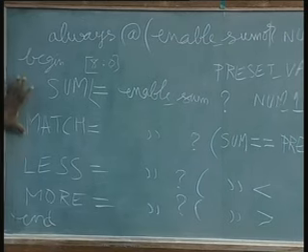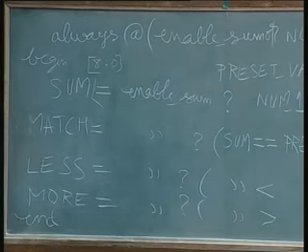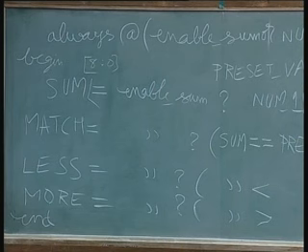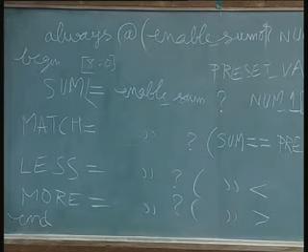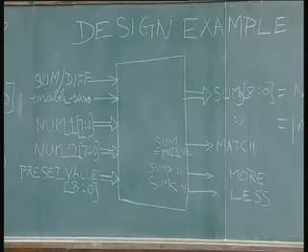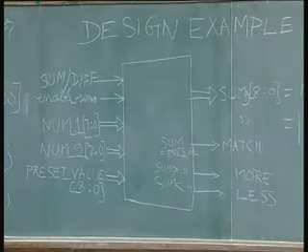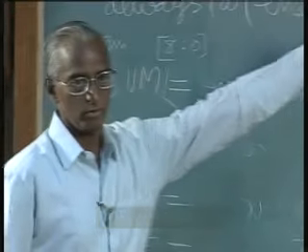But when you put assign statements, it keeps on churning continuously because it is precisely the gate that is going to be mapped onto the device. So it will be working all the time. If a circuit is working, it consumes more power. So the always block is preferable because it will work only when any change is encountered.